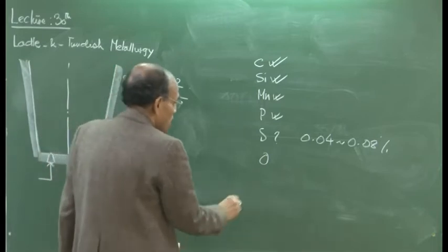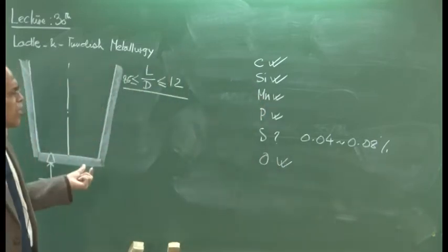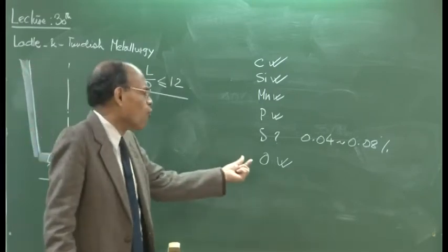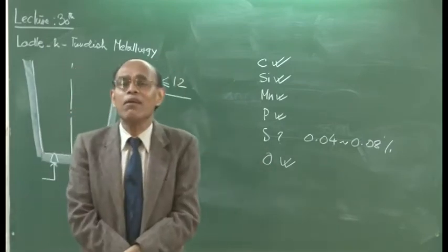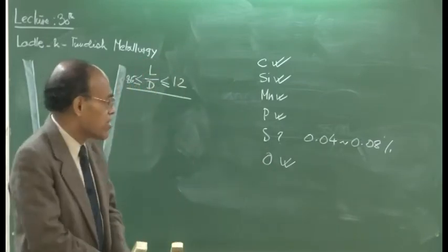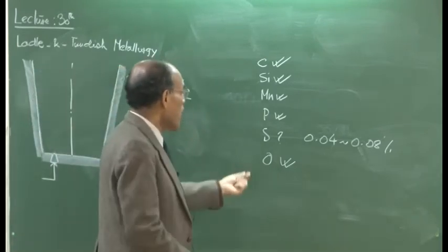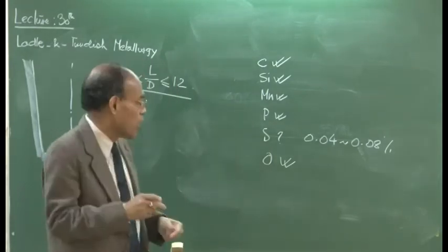So, dissolved oxygen is therefore also correct, or if the deoxidation has been done approximately, it may be very close to the actual one, but may not be absolutely the precise desired level of residual oxygen. So, there may be some correction, some additional trim adjustment in composition, that is what we say.